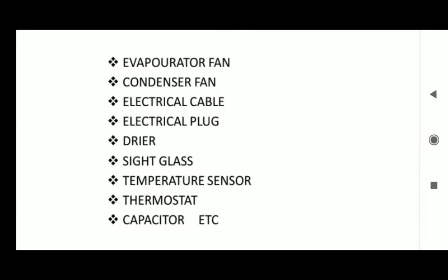Normally if I'm in a class, I would have asked a question now. The question I would have loved to ask is, if you must install a filter, where will you put the filter? Is it the supply line or the return line? But I will give you the answer. The filter is always installed in the return line, because the heated air and the dust within the place are being sucked by your AC. So before it enters your AC, you need to take care of the dust in the air. When you take care of the dust, the evaporator does well to cool the air, then passes it into the space which you enjoy, and the quality of air is guaranteed.